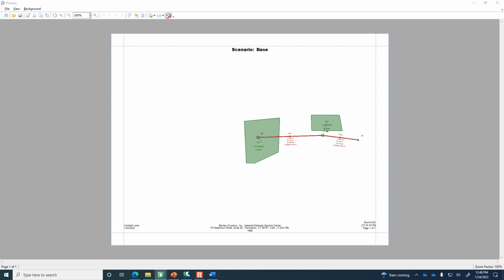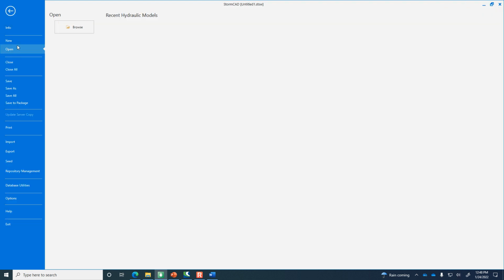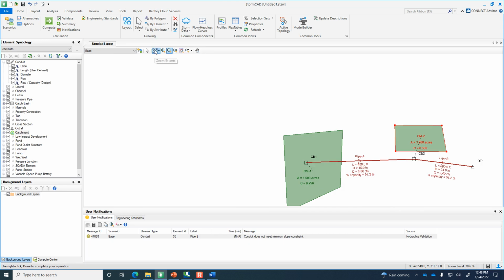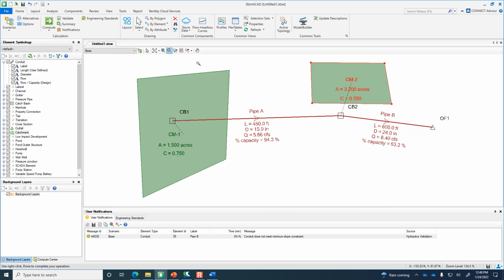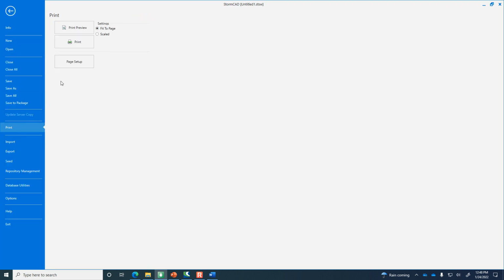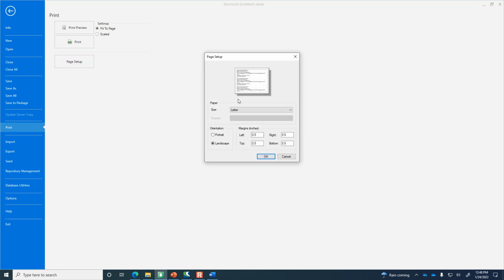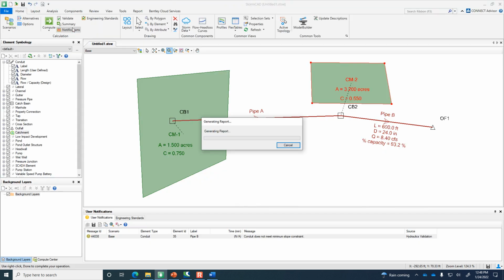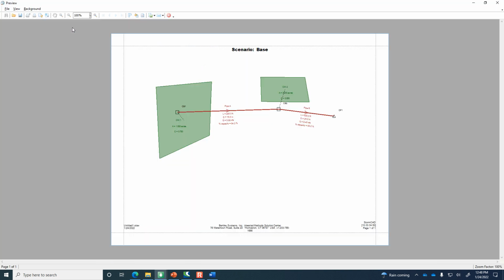So when it's in this scaled mode, it's important for you to do the zoom extents button so that your model is filling up the window, your drawing window, and then you will get, oh, not set up. Then you'll get your print to fill in the majority of the printing space that's available. It's not perfect at it, but it does better.